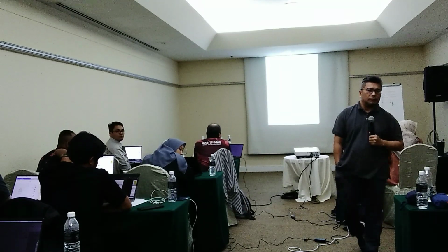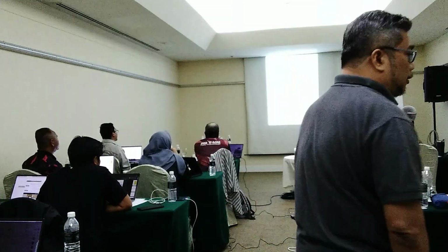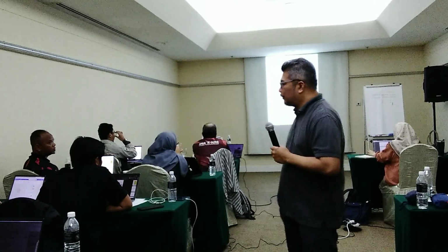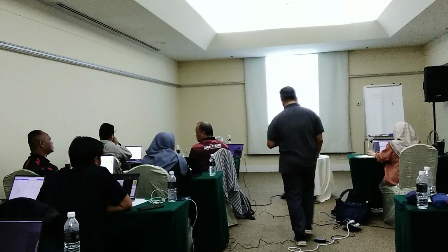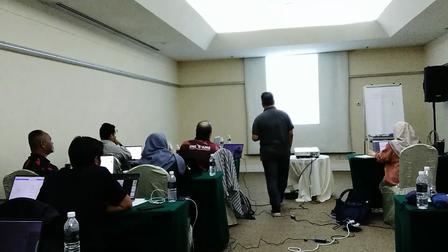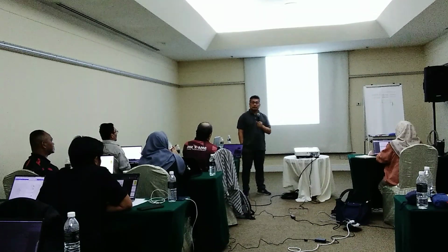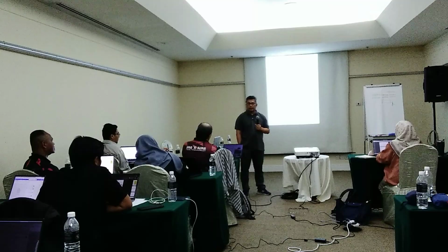That one scores 9 on the severity or RPN. On any aspect of risk, on severity, on occurrence, on detection, in any of the three aspects of risk, if you have one input variable with a 9, then automatically you need to reduce the risk. Okay, you need to reduce the risk.